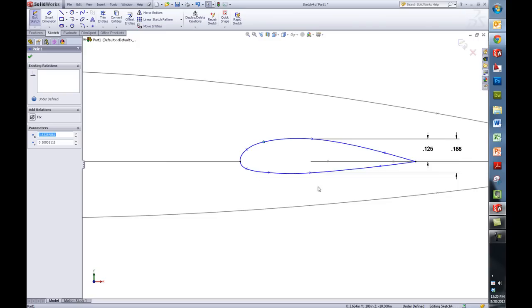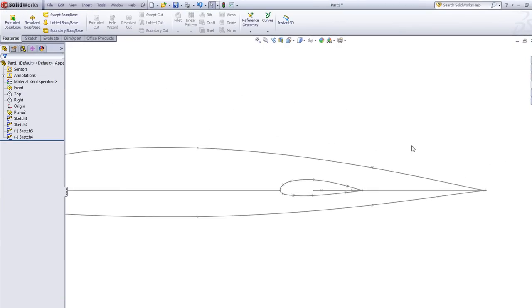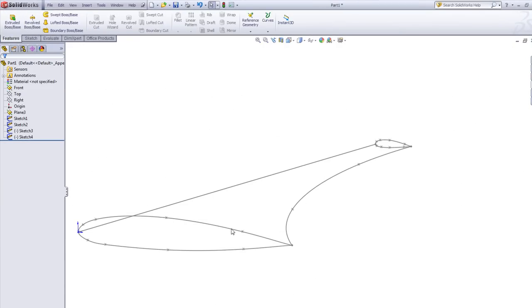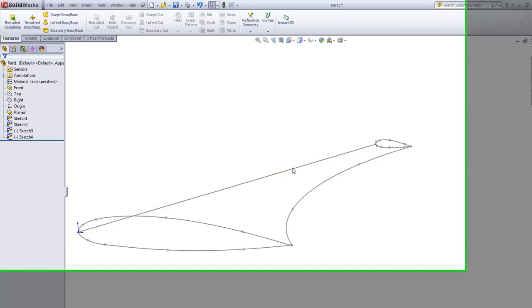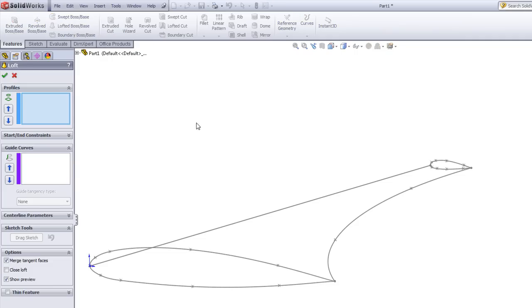So once I have those 4 sketches, if you will, again, the starting profile and end profile, and then the shape of the leading edge, which for this wing was easy because it was a straight line, and the contour of the trailing edge, then we do what's called a lofted surface. So I wanted to show you how that looks. I'm going to create up here, if you can see my mouse, a lofted surface here.